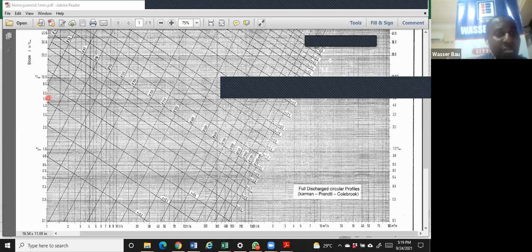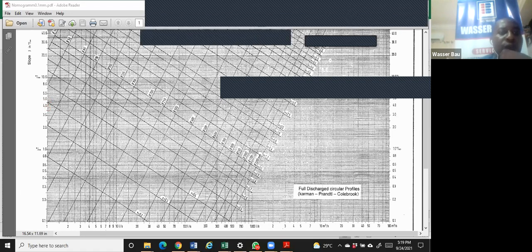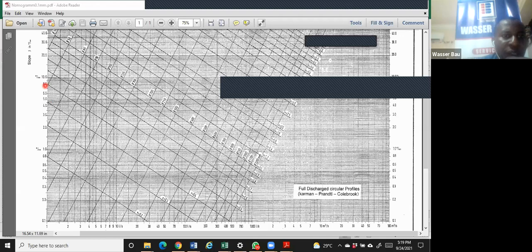Under design is, in German we say, verboten, unacceptable. It's absolutely not acceptable. So here, this is 5 per mil, falling between diameter 50 and diameter 65, so I'll choose diameter 65.